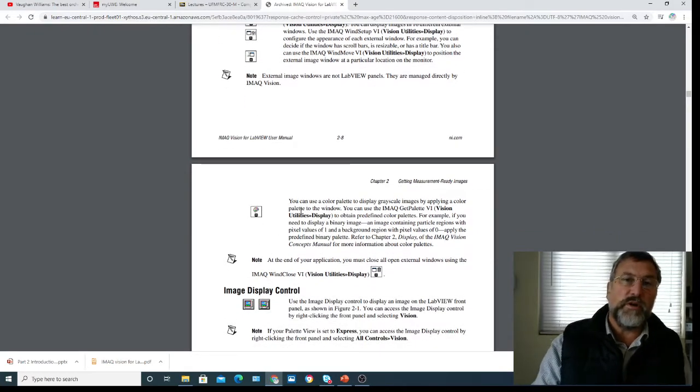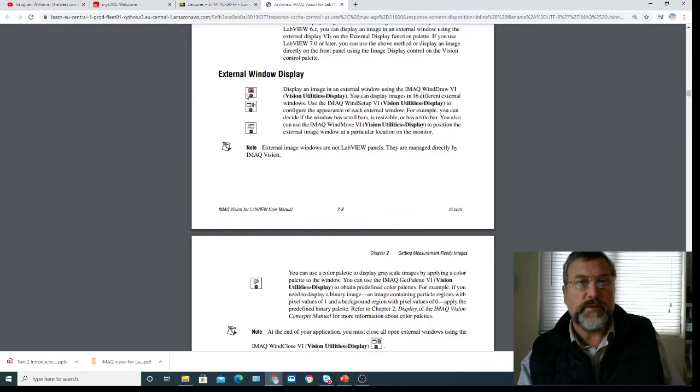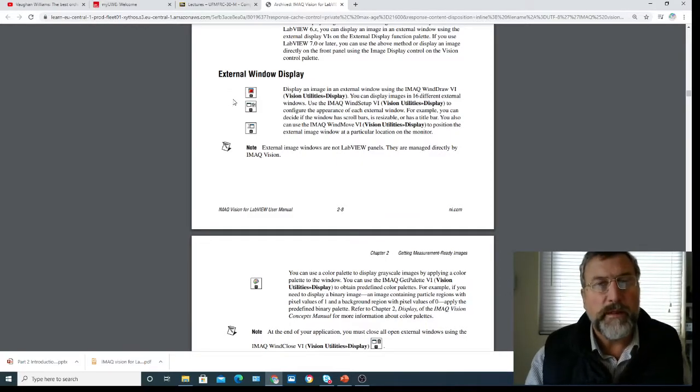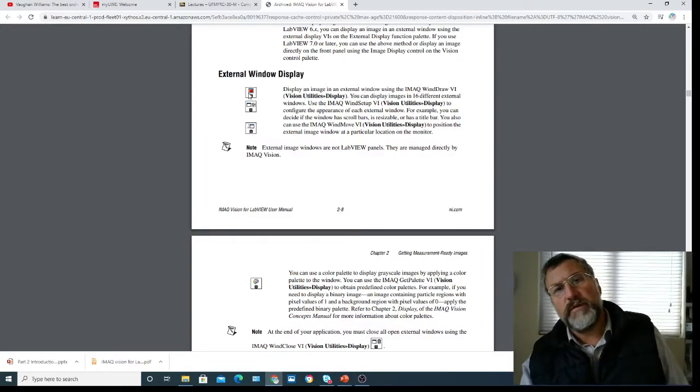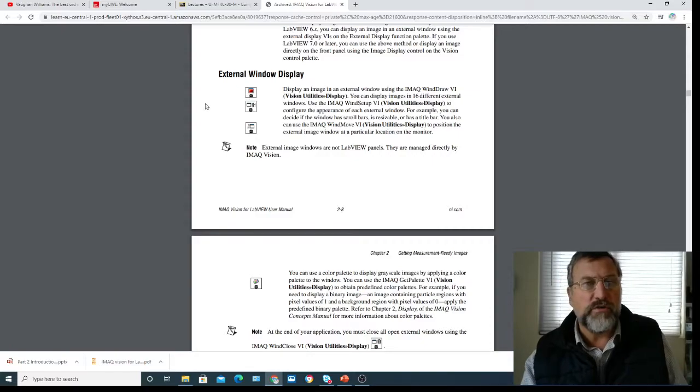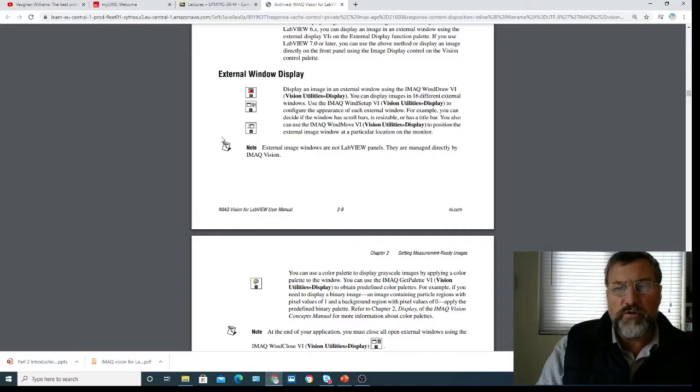One thing you can do a lot of the time, as I mentioned before probably, is you get the connector tool, the wiring tool, you just hover over the VI, you should see the connection, you right click, and then you can go to create on the menu that comes up, and you can create controls like inputs, and they will have the right type of data for that input on the VI, and they will save you some work, so you won't always have to create inputs and then wire them, and it will do it for you.